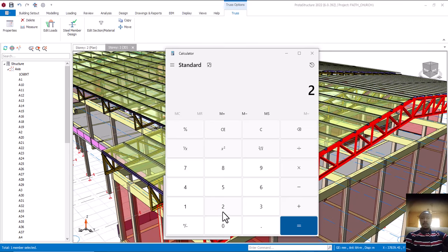Is that okay? So when we say based on Eurocode, our factor for dead load is 1.35. Sorry, let me cancel this. To factor the load for this calculation, based on our calculation, our dead load is 0.2 and our live load is 0.6, isn't it? So that is fine. So let's now factor it, factored load now, based on Eurocode.